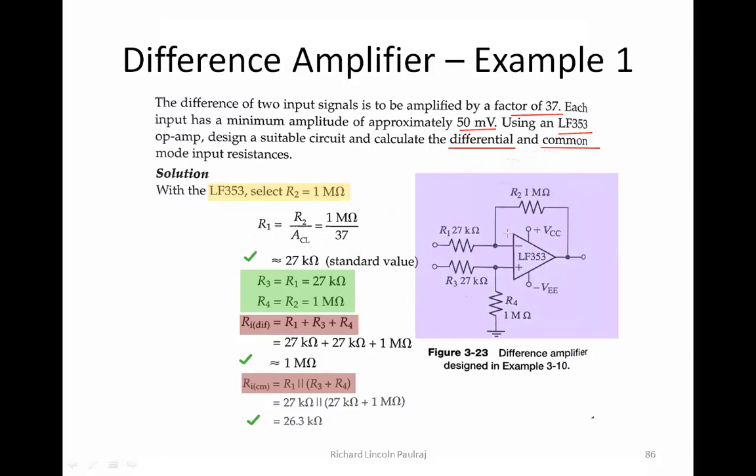It's very simple. You give a negative feedback with a resistor, the input has a resistor, inverting and non-inverting, and you have an R4 resistor. So just these resistor values, you can put in your circuit. So that is actually called design. Okay, so that completes this problem, right? Design. And we have found out for both differential and common mode combination. Any doubts here, students?